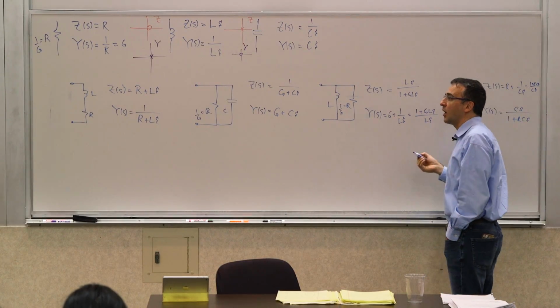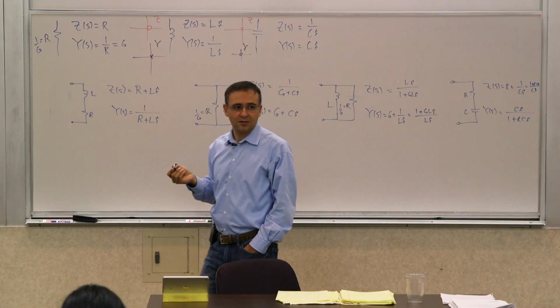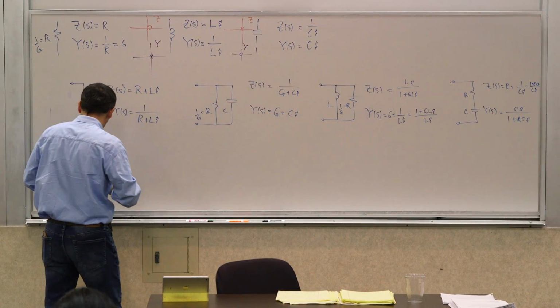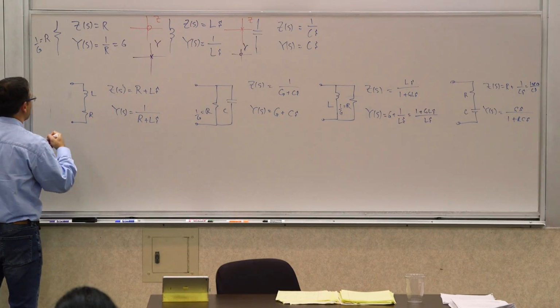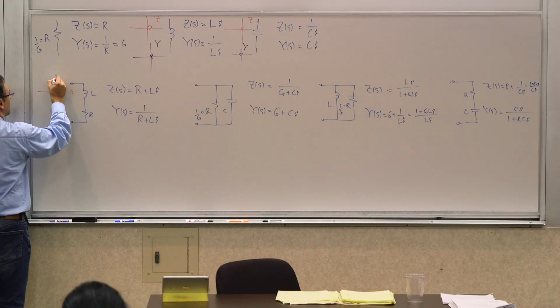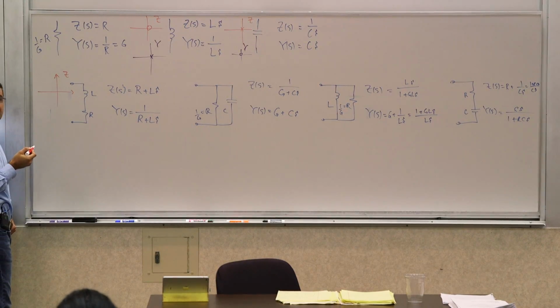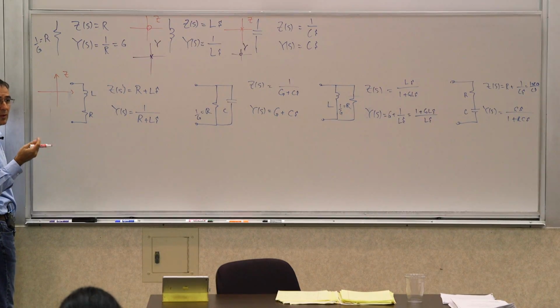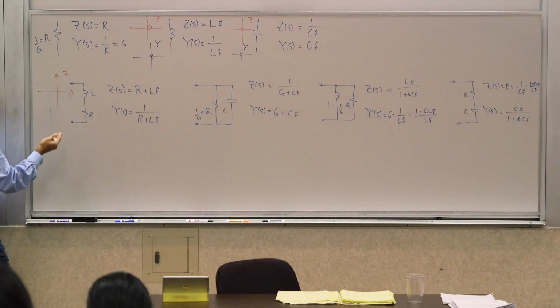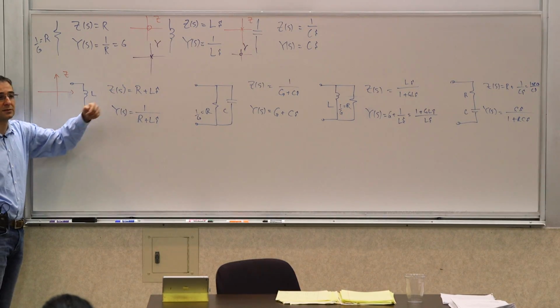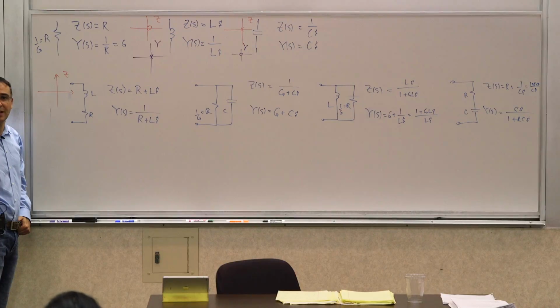Again, they're not that surprising by themselves, not that particularly profound. But you can also think about it in terms of poles and zeros. So if you look at the Z, for example, here, what do we have? If we are dealing with positive values of R and C, where is the root of this? Where is the 0? Left half plane or right half plane?